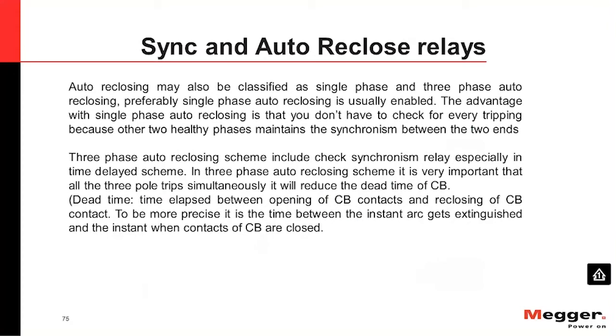Auto-recloser also can be single phase or 3 phase, meaning that it will work as a single phase auto-reclosing. In Europe, as far as I know, when they have a fault, they usually trip the same faulty phase, but the other 2 phases will still be healthy. So the same phase will be auto-reclosed.